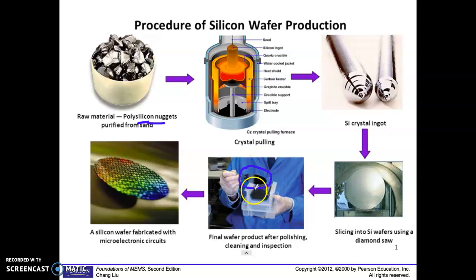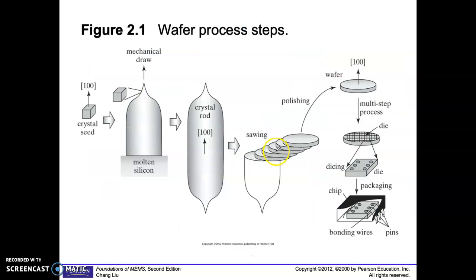So there will be additive process, substrate process, and the lithography process on top of the silicon substrate. Okay, so this is again the process, and you're going to have the mass fabrication at this wafer. So in this wafer they choose 100, and then after the fabrication process has been completed, they're going to slice to make it into dies and then package it. So this is what you see from all the chips. Inside the chip actually is a silicon wafer that is from the sand.